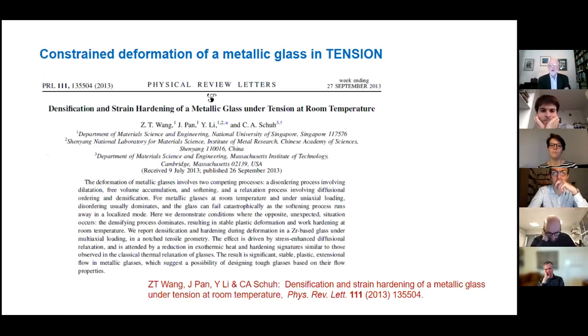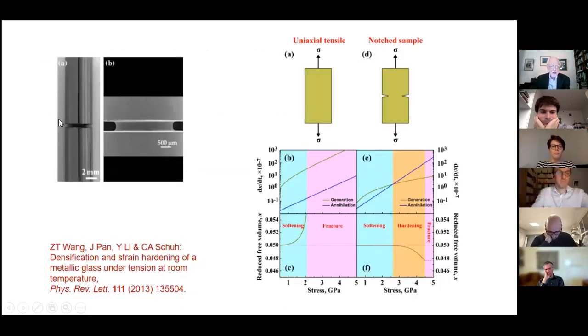Well, there's this work from some time ago, Chris Hsu at MIT is involved, where they looked at a metallic glass in a very particular test geometry, which is a simple enough one. It's a cylinder with a machined notch. You then put the cylinder into tension, and you compare the material that deforms in the region of the notch, plastically deformed, with what would happen without any notch. Well, without the notch, you'd get a rather low yield stress for the system, the material flows, and the strain could be large.